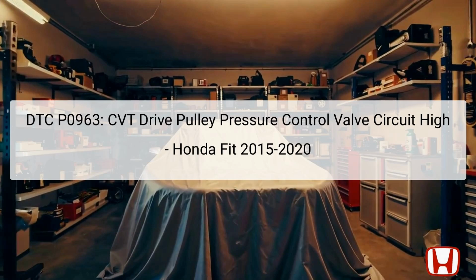The Diagnostic Trouble Code, DTC P0963, pertains to the CVT, Continuously Variable Transmission, Drive Pulley Pressure Control Valve Circuit, high issue in the Honda Fit models from 2015 to 2020. This code indicates an electrical circuit malfunction, specifically in the pressure control valve circuit related to the CVT. It's important to understand that this error is distinct from mechanical problems within the transmission itself.